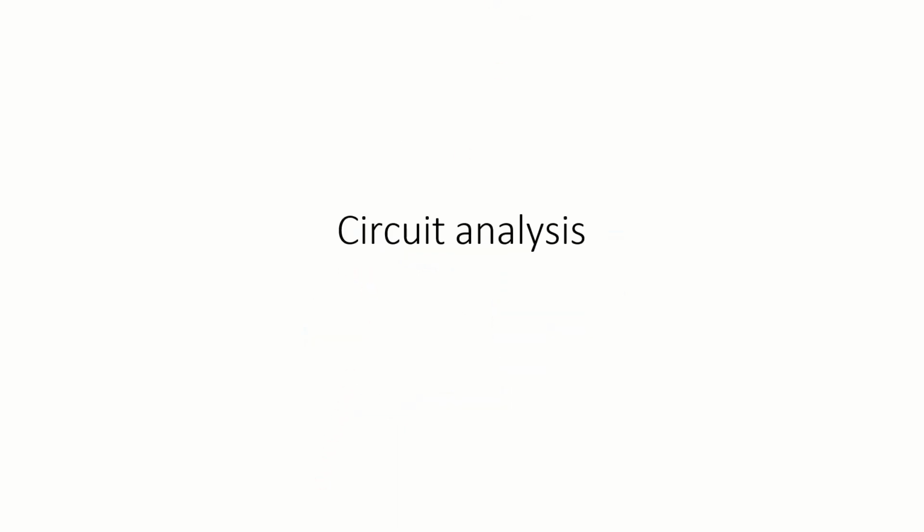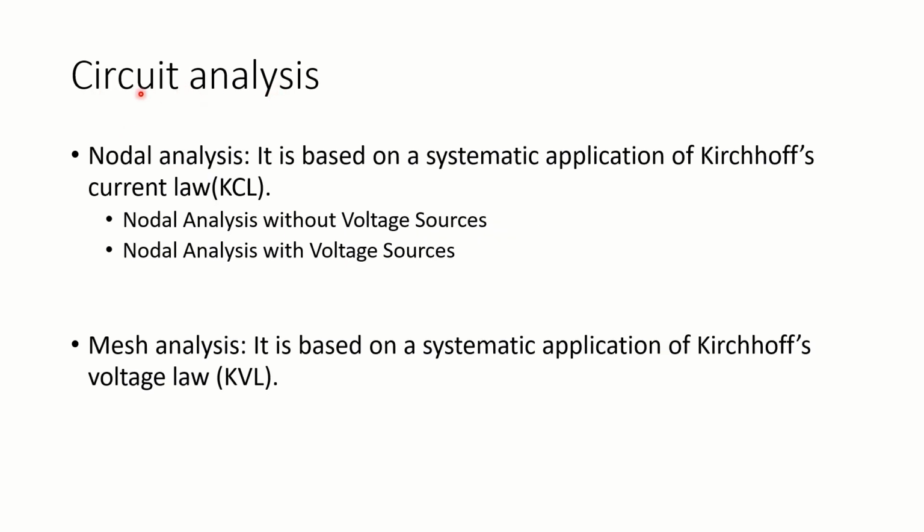Now we are going to talk about circuit analysis. So what is circuit analysis? Circuit analysis is divided into two parts. Number one is nodal analysis. What is nodal analysis? It is based on a systematic application of Kirchhoff's current law, or KCL. What is KCL? KCL states that the amount of current entering a circuit is equal to the amount of current leaving the circuit. So let's visualize this circuit.